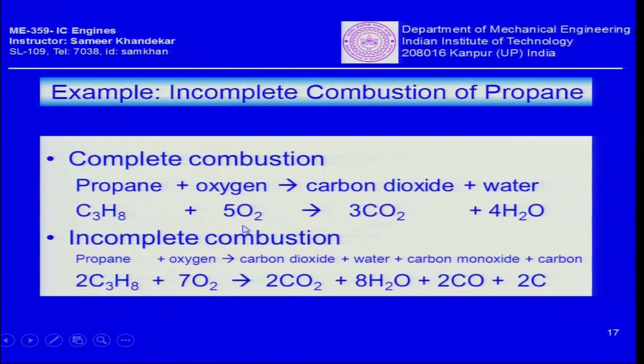If you take air, then you put a bracket here, and there will be 3.76 nitrogen inside the bracket if you want to burn the same thing with nitrogen, and of course nitrogen will come out on the right hand side of the product. So C3H8 oxidizes with oxygen. You are doing complete combustion, and it is a pure hydrocarbon, so you will get CO2 and H2O.